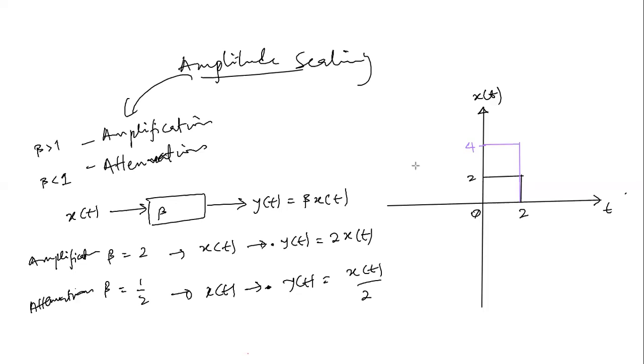That is why in our regular mobile communication, we use the lower frequencies for coverage, to communicate over a wider range. And then we use the larger frequencies to optimize for capacity, because we can only cover very short distances.